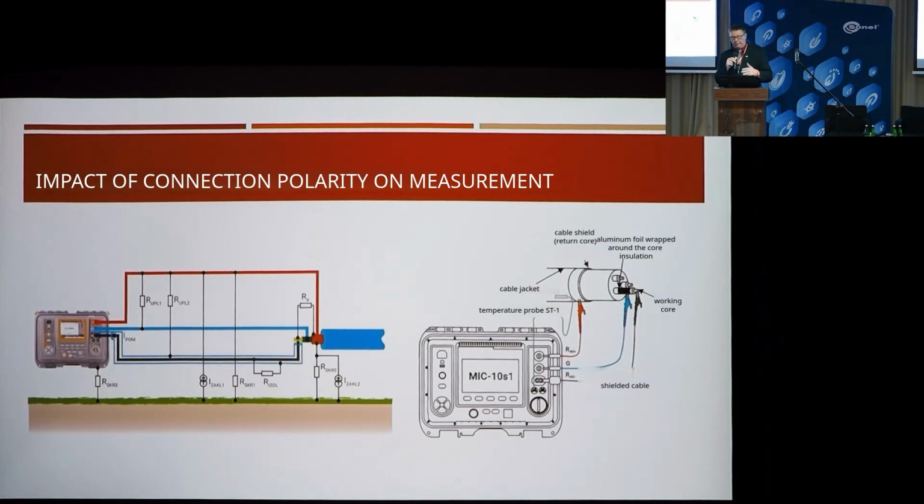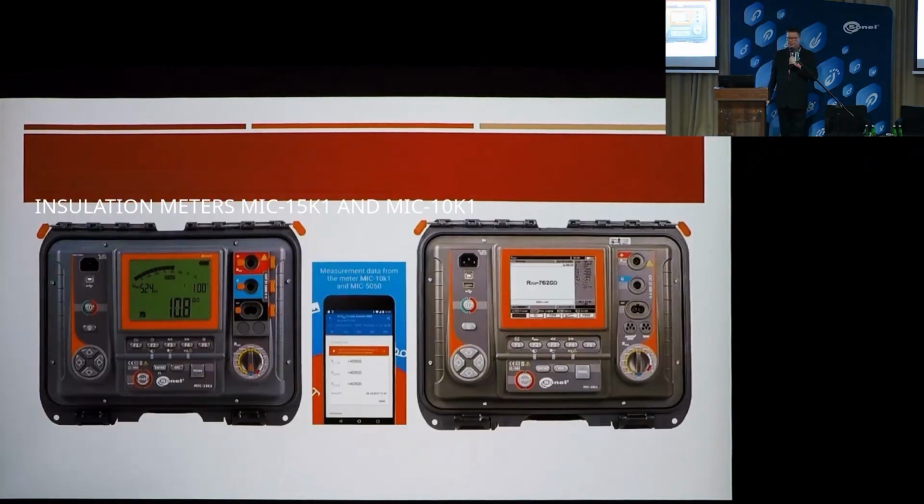What else? Sometimes questions come up here about why some measurements differ from one another. As I showed earlier, we're measuring currents on the order of 9 nanoamps. That's already enough. So notice that even if we just move closer to an object like this, we're already introducing a change in capacitance. So these are the kinds of things you really have to pay attention to.